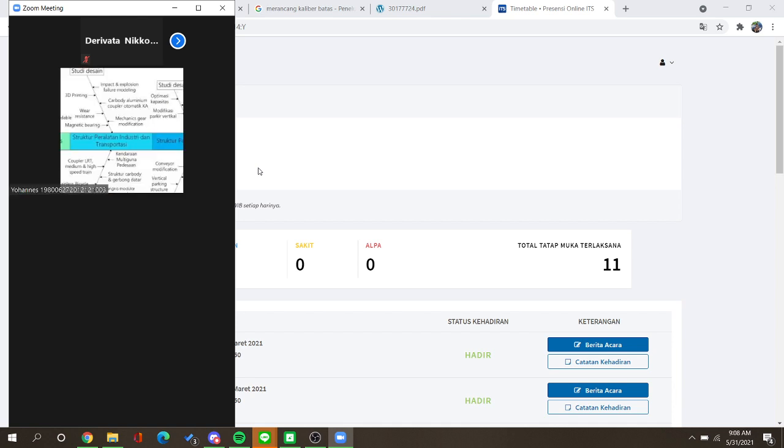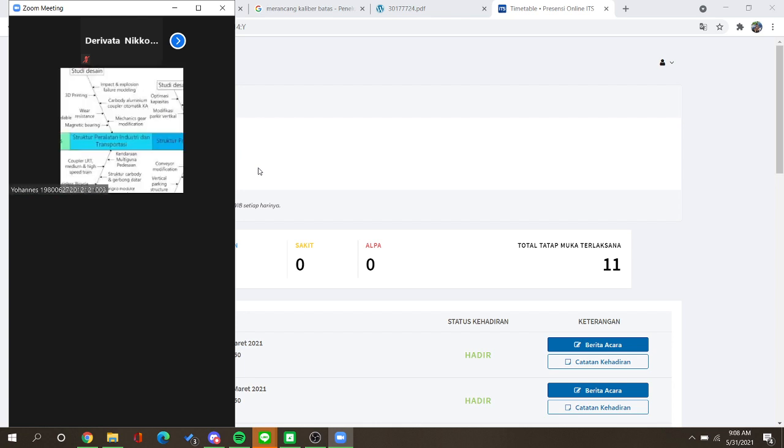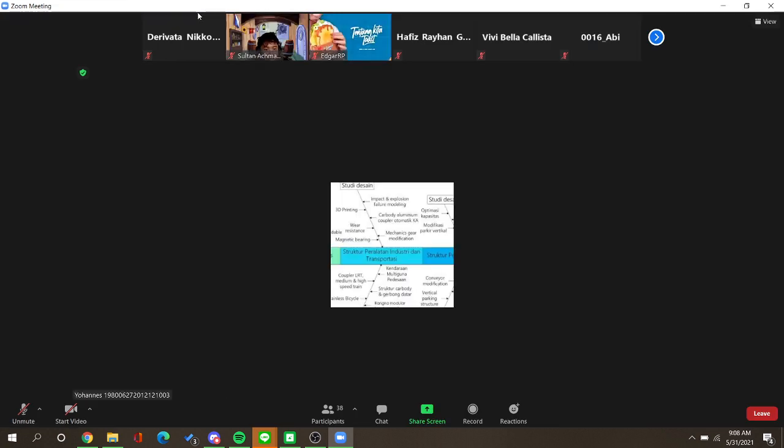Okay, so do you mean that if we change the load into torsional load, then how about the correction factor? Is it the same? We use just like the axial, or we need to put another correction factor? Is that what you mean? Yes, sir. Okay, so just like I mentioned previously, for torsional and shear load, for ductile material, we use correction factor of 0.5.